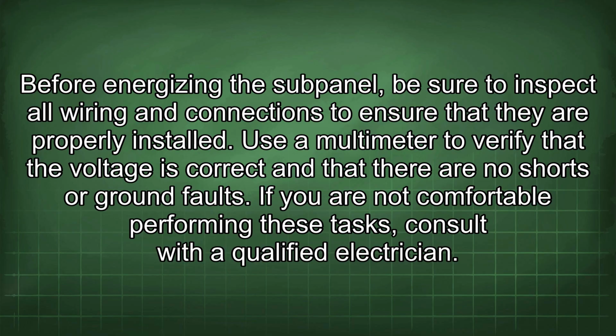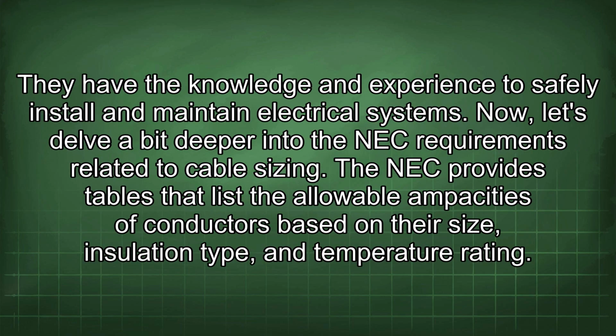Before energizing the subpanel, be sure to inspect all wiring and connections to ensure that they are properly installed. Use a multimeter to verify that the voltage is correct and that there are no shorts or ground faults. If you are not comfortable performing these tasks, consult with a qualified electrician. They have the knowledge and experience to safely install and maintain electrical systems.